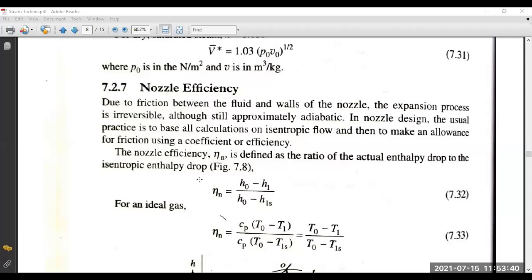If the semi-vertical angle is large, there will be flow separation from the wall with the formation of eddies, which entails heavy loss. If the angle phi is small, the length of the nozzle becomes too large to provide the desired exit flow area, causing more energy loss due to friction. Alpha varies from 5 degrees to 8 degrees.